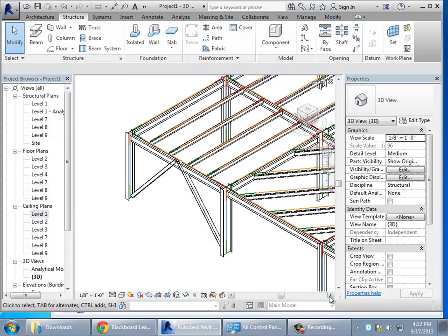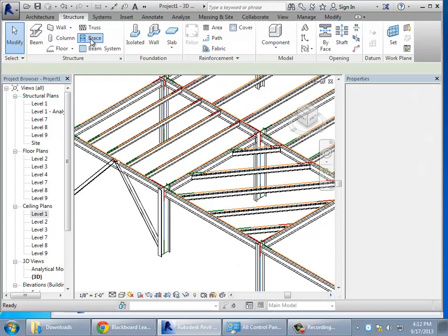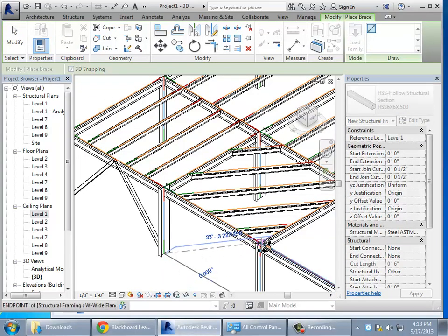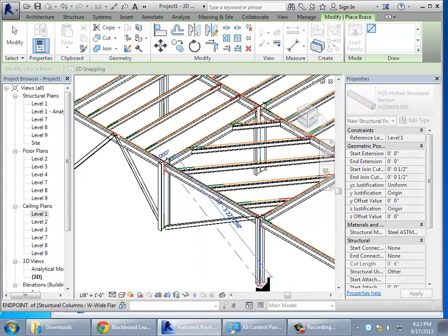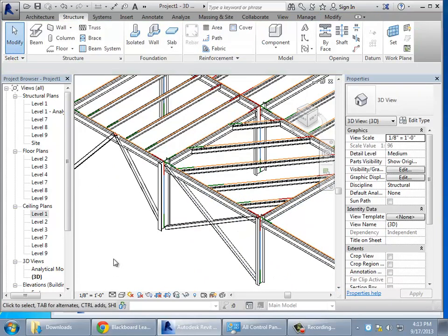So whether you have K braces or whether you have X braces, again, if I had an X brace, I might just do something like this. And again, this won't look quite right as a start because there's going to be a little bit of cleanup at those intersections. But what will happen, and this is something you have to watch out for, even as you model, this gets to the whole level of detail argument. As you're designing, and first just trying to work out how the building is going to be and how the structure is going to work at a first level, it's probably not worth your while to go through and model in great detail every bolted connection. So you want to sort of get the big elements in place, sort of understand what the sizes need to be. If those are all looking good, then we'll go back and at another higher level of detail, start adding that real fine fabrication detail.